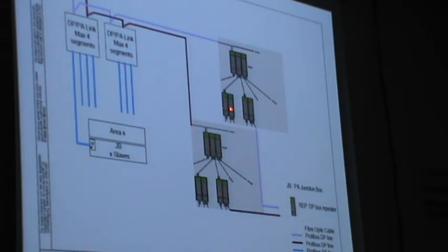And this one cable can communicate with up to 32 devices. 32 instruments, motorized valves or PLC, can be communicated with this cable. The PLC can be one, plus you can add the motorized valves with that. So 32 can be communicated with one cable.